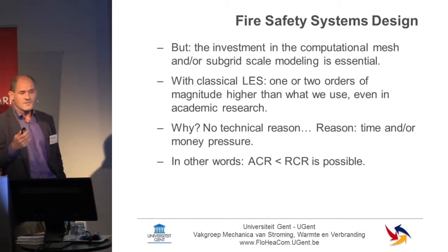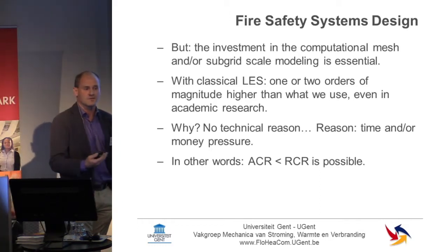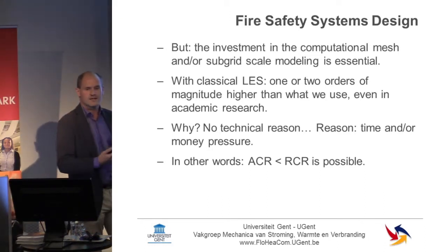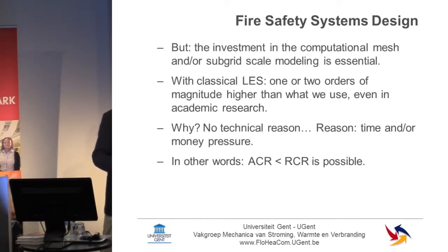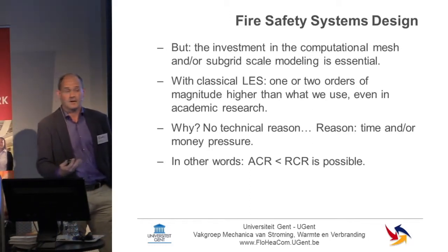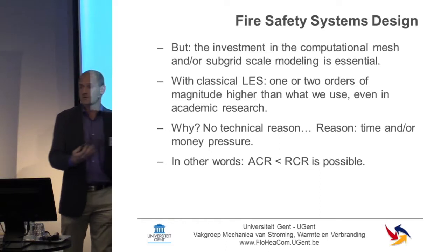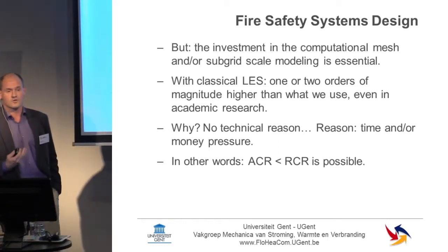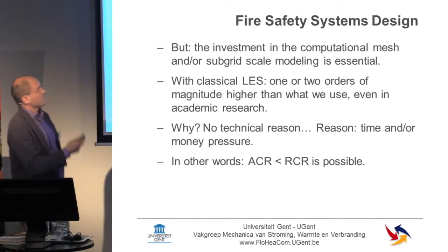It's an acronym, which means that the largest turbulence, eddy is a word for a turbulence in English, is simulated or followed. Now, if you want to follow these swirls, your computational mesh has to be fine enough in order to follow it.